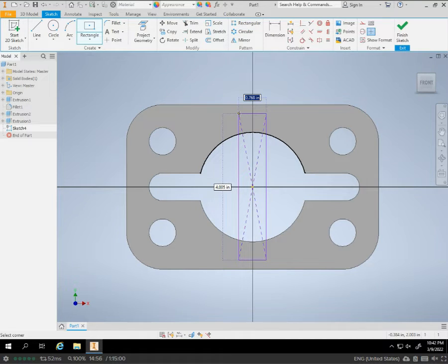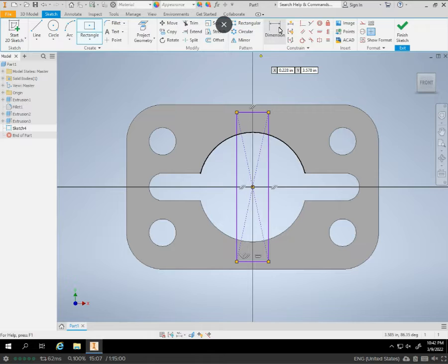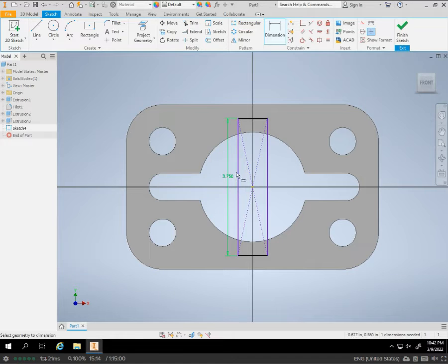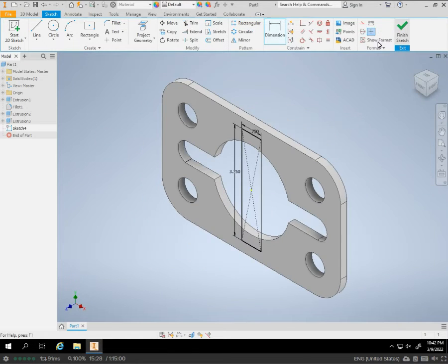Well, it should really be about 3.75 tall. So we're not gonna change two of the numbers. And it's 0.75 wide. So we just kind of put it in place first. Then use our dimension tool to adjust the numbers. So it's gonna be 3.75 this way, 0.75 this way. And because it's coming from the center, it automatically adjusts. So we hit check mark,